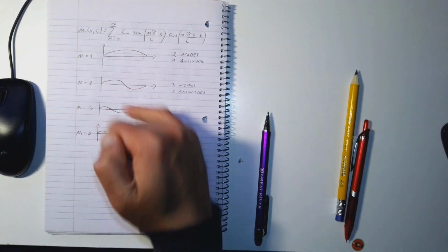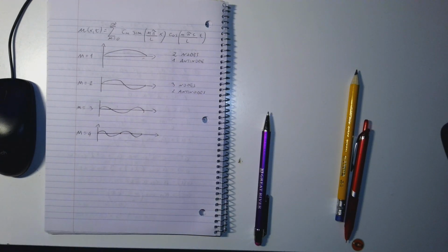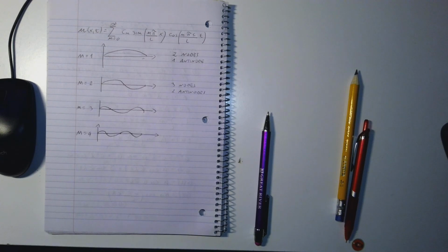Now, the amplitude of displacement decreases when we move from mode 1 to mode 2, mode 3, and so on. This is the same as what happens in a discrete system, but in particular for continuous systems, when we look at the amplitudes of vibration, the first mode is typically the one with the highest amplitude. So we need to look at those with the highest amplitude of vibration, again because from a structural point of view we don't want too much strain. Make sense?